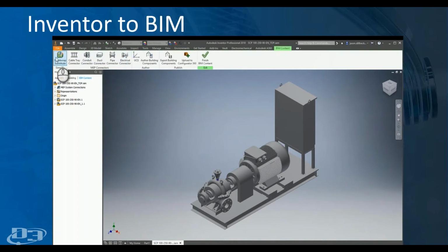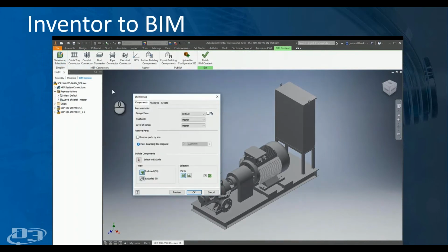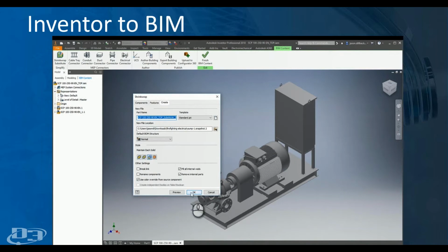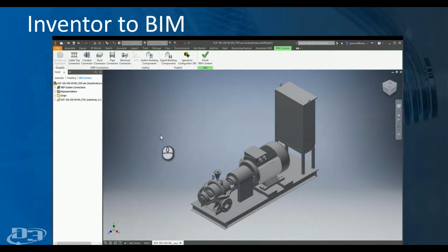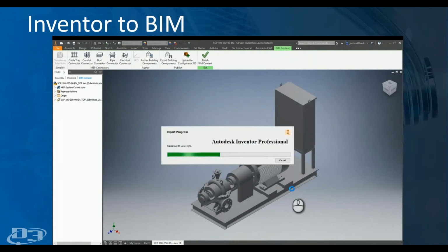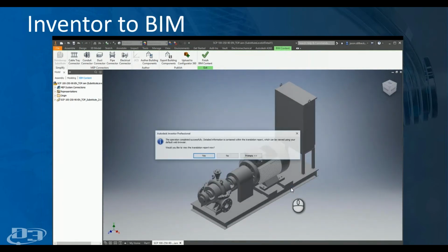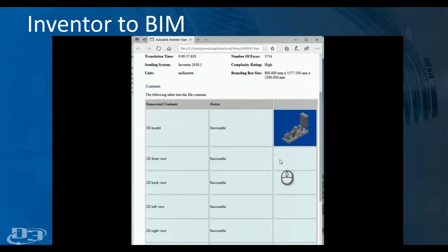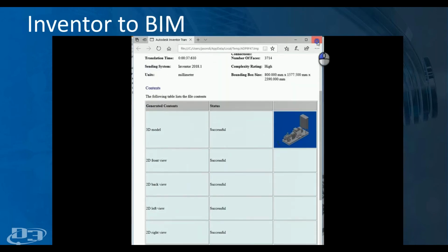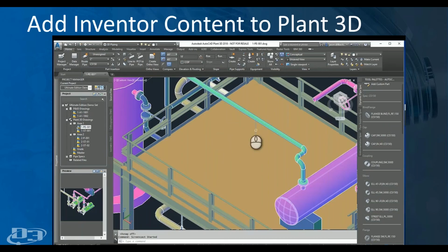If any equipment is needed, has been created in Autodesk's Inventor, just use the BIM content environment built in. Make sure to take advantage of the shrink wrap substitute to reduce the model complexity and help model sizes in our Plant 3D program. We can create pipe connectors for use in our Plant 3D model, although it isn't necessary because we can also add these connectors once in the Plant 3D program. Start the Export Building Components command and choose an ADSK file. When complete, a report is created for your review.